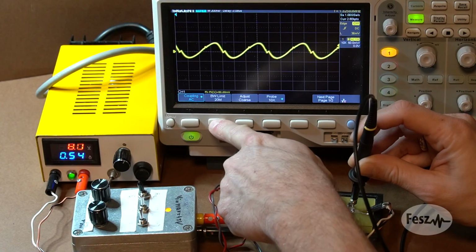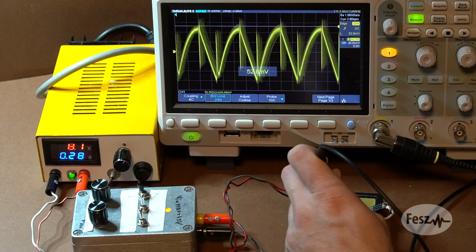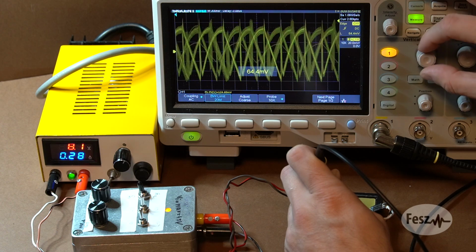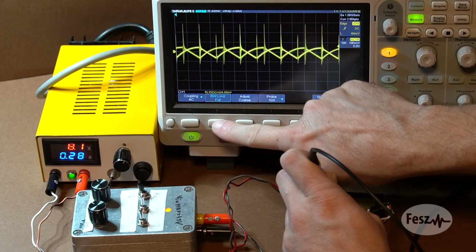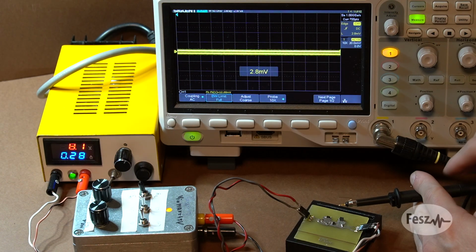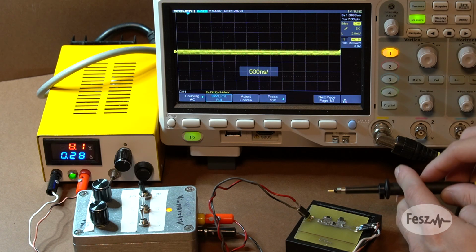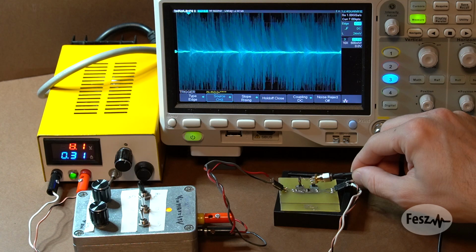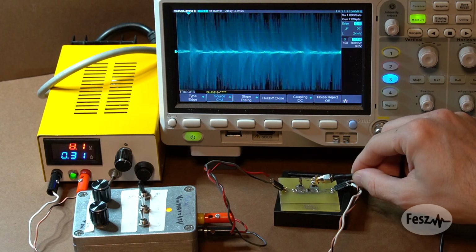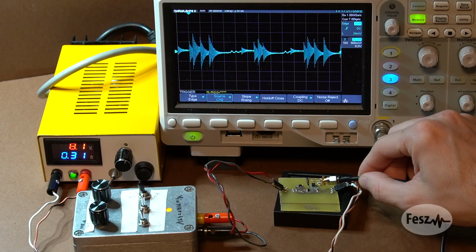To start things off, it's important to understand that electrical noise will exit the power supply in multiple ways. You have your conducted noise, whatever exits through the input and output wires, and radiated noise, whatever exits in the form of a field. In the short range or near field, this will take the form of electric and magnetic fields, and in the far field, the two combine into a single electromagnetic field. Both of these can and will be problematic in the real world.